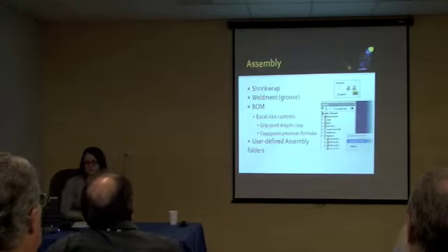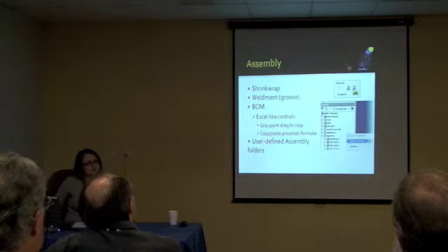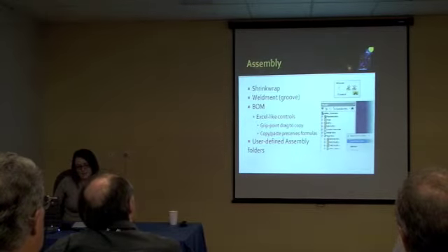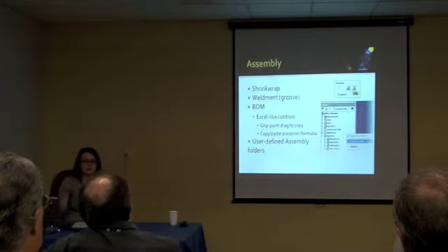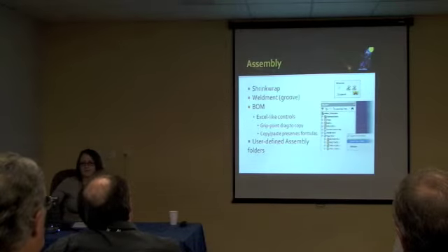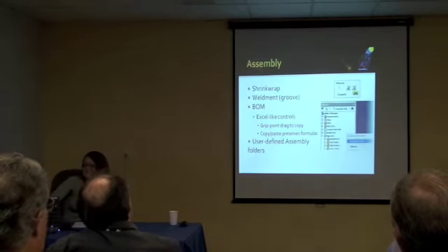Okay, weldment. There's been a little change to the groove weld, groove in brackets there. They've added the option for radial fill. So instead of weldments having to do this really ugly fill in one direction and then fill in the other direction, you can now just tick this radial fill option and it'll fill it up for you. If you've been using any welded assemblies, you'll be cheering, so I guess nobody's using welded assemblies.